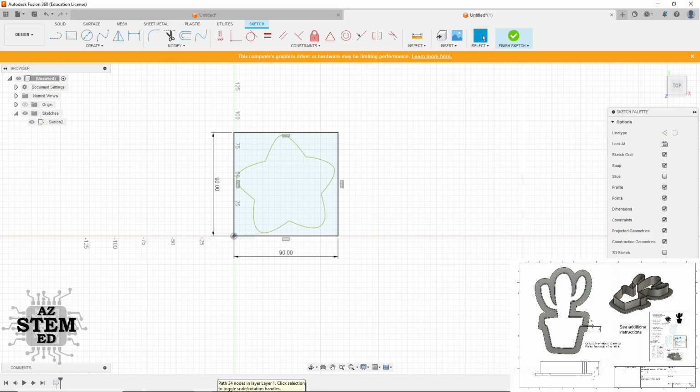That looks great. And then let's not finish the sketch yet. My box is going to get in the way, so I'm going to trim it, and I do that using the scissor tool. If you don't see it here, it's going to be in modify. It's trim. So I'm going to erase all these and get rid of them.